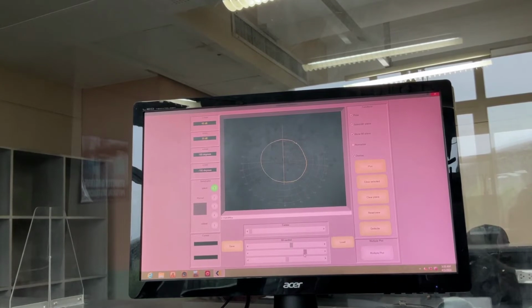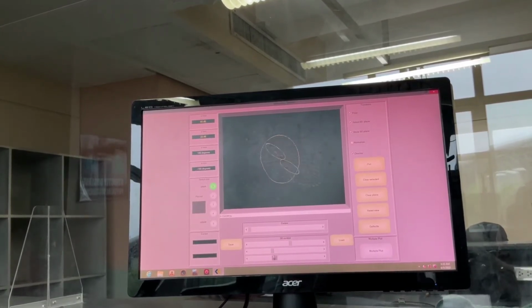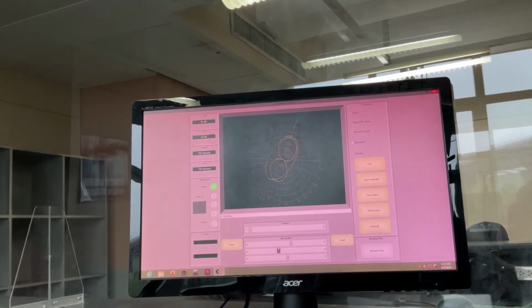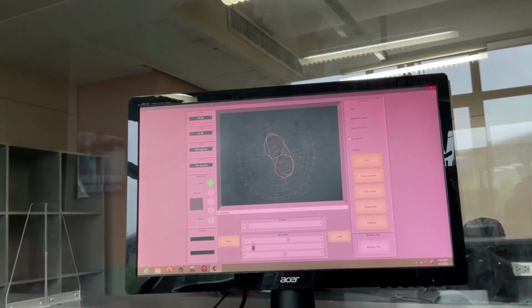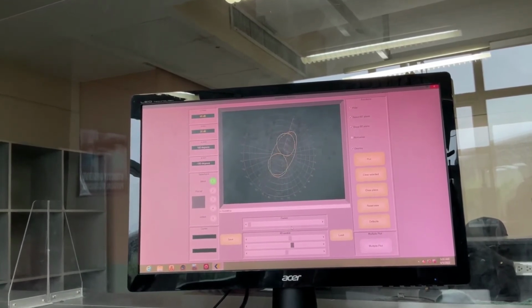The difference of the vertical and horizontal polarization of the dipole antenna is more apparent while using the 3D feature of the radiation plotter. The radiation of the vertical dipole antenna is radiated virtually equal in all directions, while the signals radiated from a horizontal dipole antenna is at maximum in specified directions.